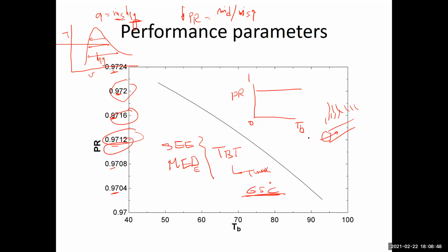If the seawater is inside the tubes, then you can do what's happening in MSF units, where you have balls like squash balls. Normally, I have some of them in my office, they are orange in color, just like a squash ball in size, and they are not very soft, and they are admitted inside the tubes. As they go through the tubes, they rub the inner surface of the tubes and clean the tubes from inside. So it's cleaning while operating.